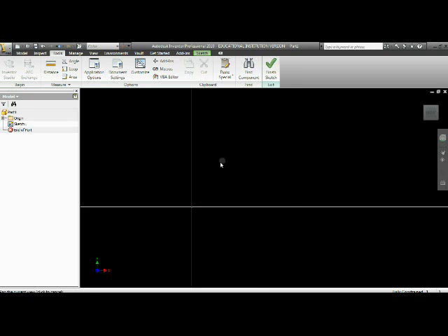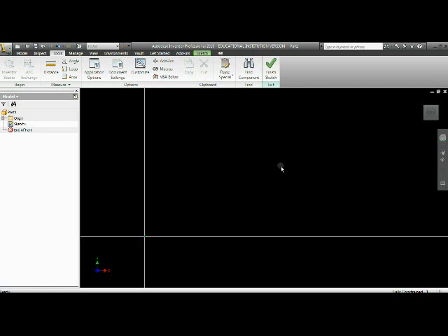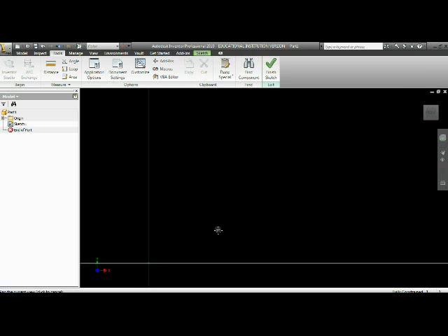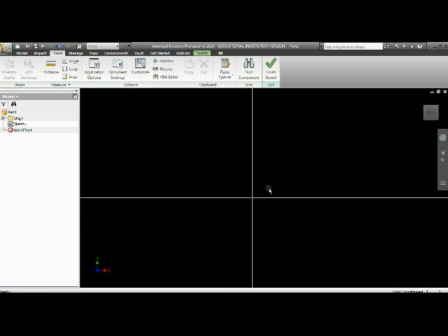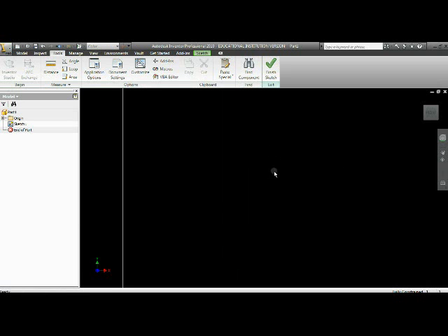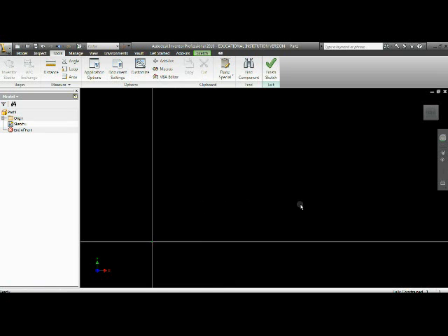So now we've got our X and Y axes and our origin right in the middle. Now, I like to draw in the first quadrant, so what I might want to do is move this origin over. Basically, I'm going to move the camera so that the camera is showing just this area right here. To do that, I have to use the pan command. Pan can be achieved by pushing the middle mouse button down and moving your cursor left and right, up and down.